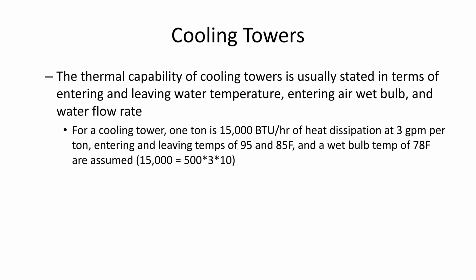So in the ASHRAE book, this is where we would go to the weather data tables in the book, and then we would look at the evaporative cooling conditions, and that's where they would give us the design wet bulb conditions, and we can get the 1% or 2% design wet bulb temperatures, because that's going to be a big driving factor.